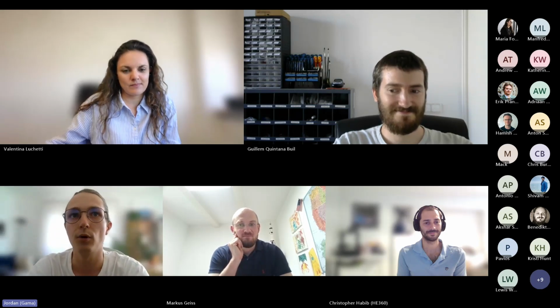Yes. Hello, everybody. I'm Jordan. I work at Gama. And before I start, at Gama we build drag sail and solar sail. So we build deployment mechanisms. HDRMs in general are central to our designs. And so basically, when we designed our product, we thought about two things. We want the product to deploy when we want it to deploy, but we also don't want it to deploy early, because otherwise, if you deploy, for example, a drag sail to deorbit a spacecraft earlier than expected, then you end the mission. So it would be a really bad situation for us.